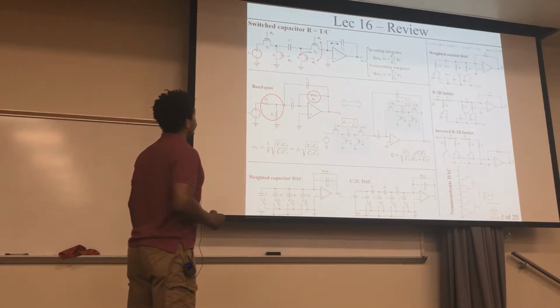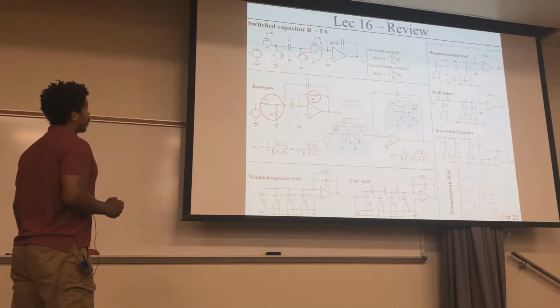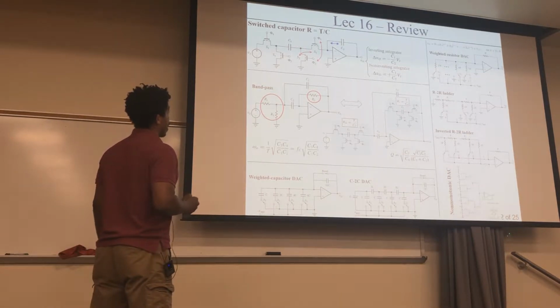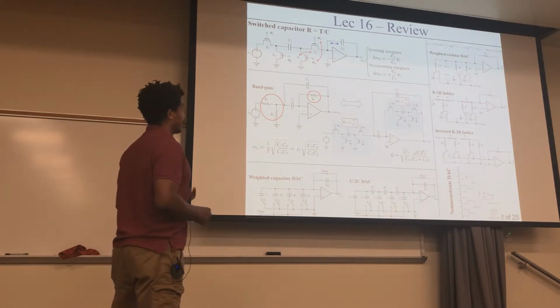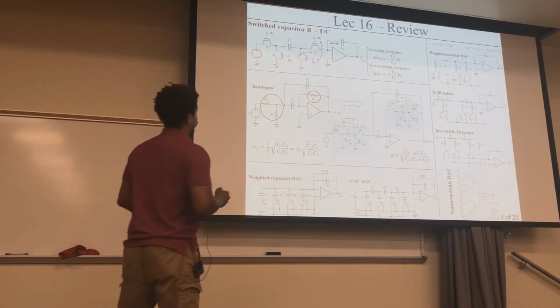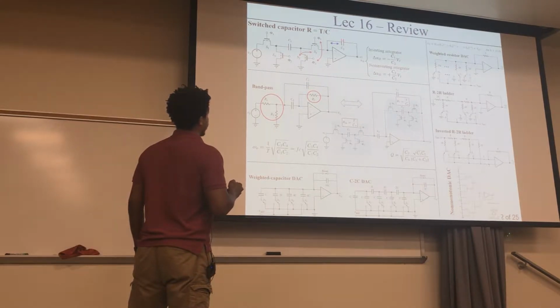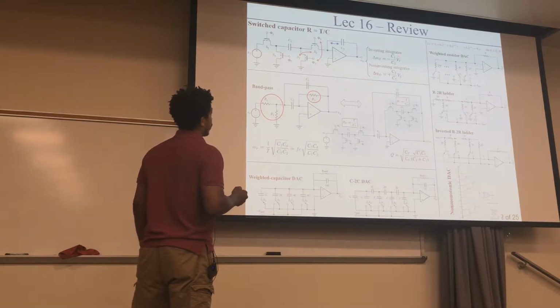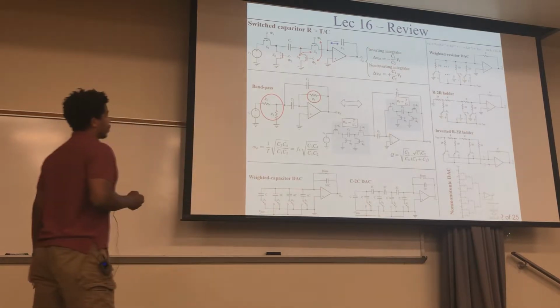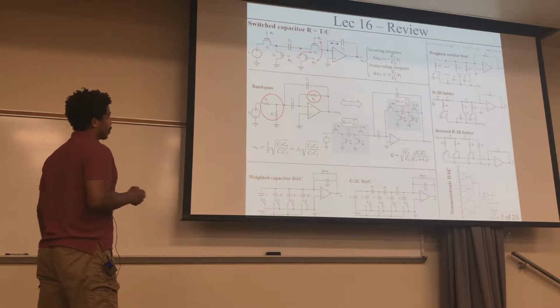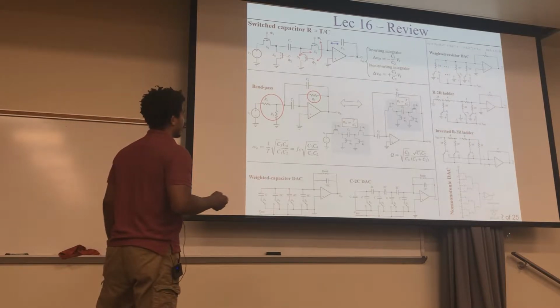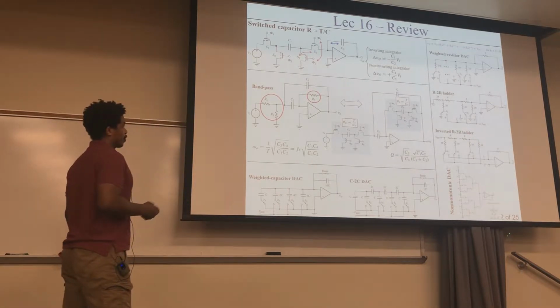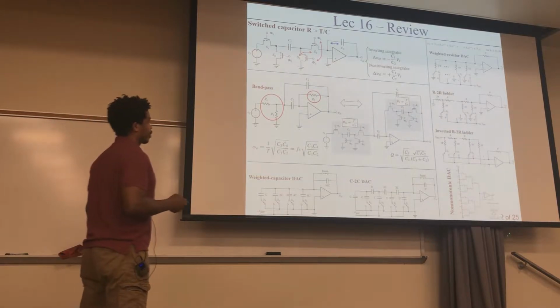For the lecture 16 review, we looked at switch capacitors. We found out that we can replace resistors with these switch capacitors, and there are some benefits to doing that. We can control the current flow going in this direction or that direction, which leads us to an inverting integrator or non-inverting integrator, right here, plus or minus. We can also look at these bandpass filters and replace those resistors with these switch capacitors right here. That allows us to do some really nice frequency tuning. It has to do with the clock frequency of our switch capacitors.